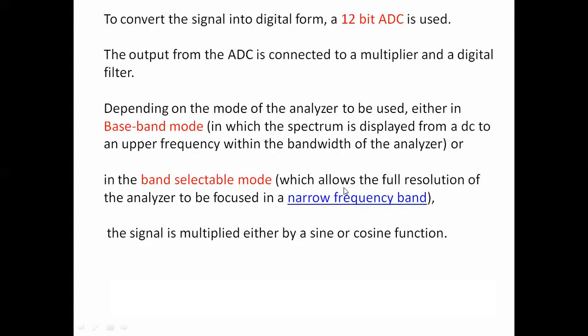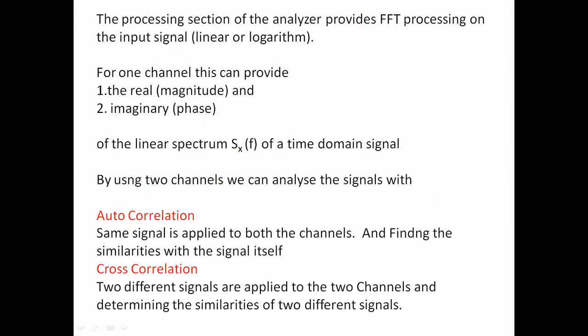After conversion by the A to D converter, the ADC, the signal will be multiplied either by a sine or cosine function. Up to now we have discussed the input section, and coming to the processing section, the analyzer provides FFT processing on the input signal.